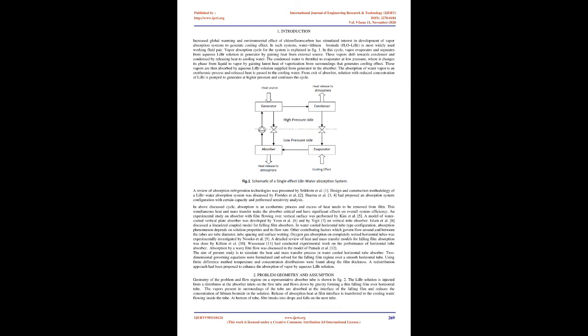cycle. A review of absorption refrigeration technologies was presented by Srikaran et al. [1]. Design and construction methodology of a LiBr-water absorption system was discussed by Florides et al. [2]. Sharma et al. [3, 4] had proposed an absorption system configuration with certain capacity and performed sensitivity analysis. In the above discussed cycle, absorption is an exothermic process and excess heat needs to be removed from the film. This simultaneous heat and mass transfer makes the absorber critical and has significant effects on overall system efficiency.